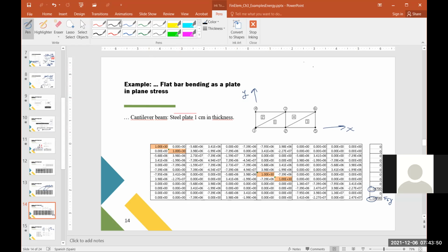For example, let's suppose that you want to analyze this case. Of course, you can imagine that around this area, the stresses are going to be very large. So what you can do is try to split the domain like this. We can go like this, and then we include elements like that. These elements are smaller. You know that in each one of these 4 elements, the strain is going to be constant. So it's a good idea to make a partition like that, or more efficient, for example, we could do a partition like this. There.